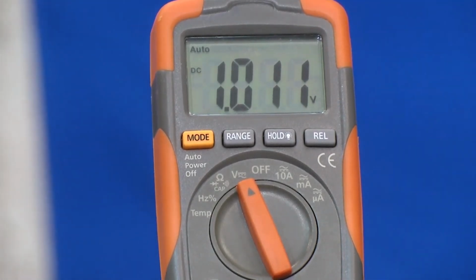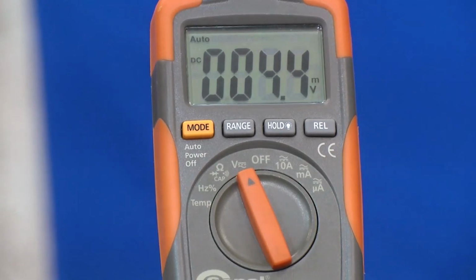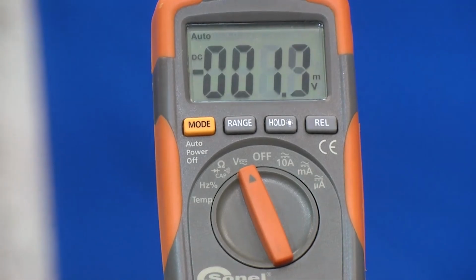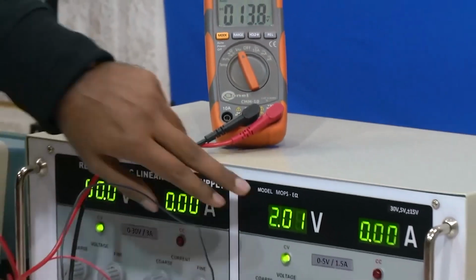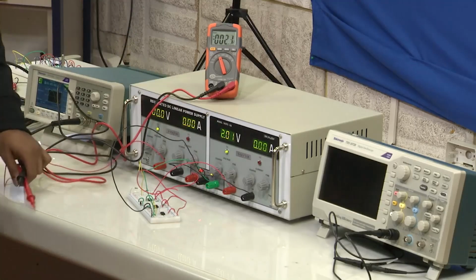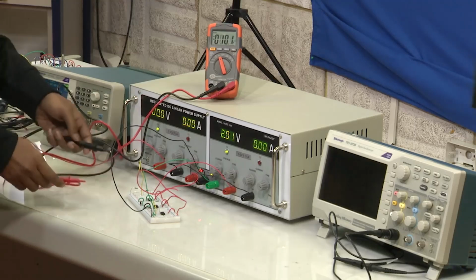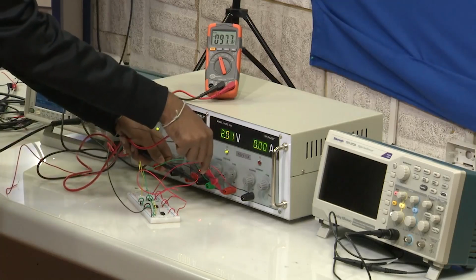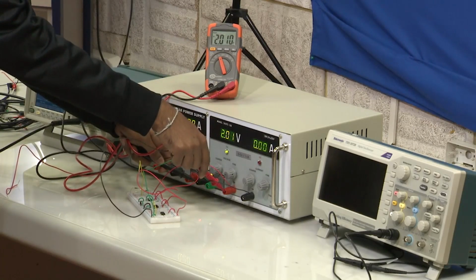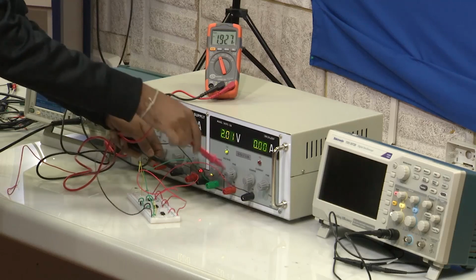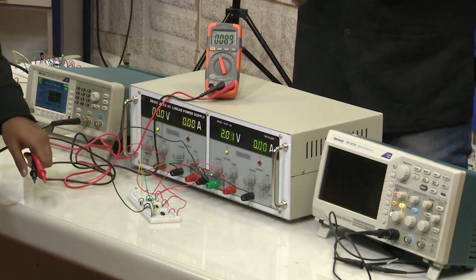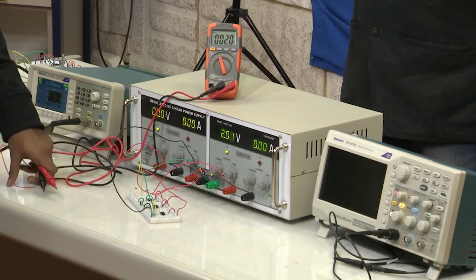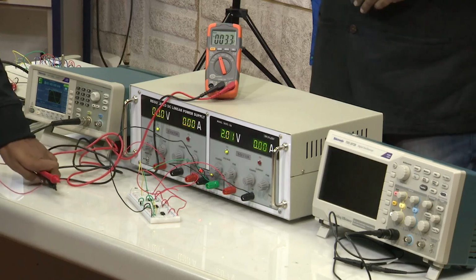1.011 volts. Now, you will say, Hardik, why do we have 1.011 volts at the output? It should be exactly 1 volt, right. But one thing is 2.01 volts is the input. Second thing is the resistors that we are assuming as 1 kilo ohm may not be exactly 1 kilo ohm, but may have some tolerance. This tolerance in the resistance will cause the output voltage to be slightly different than the expected or calculated output voltage.